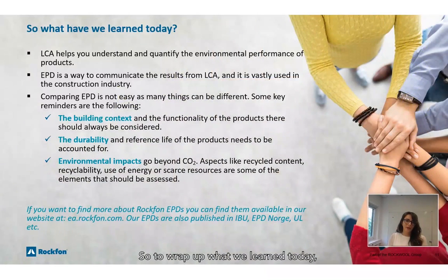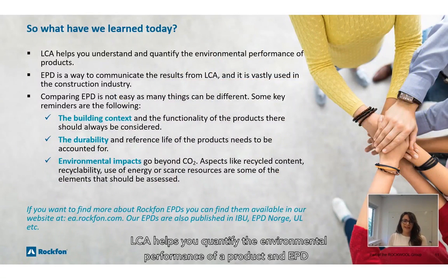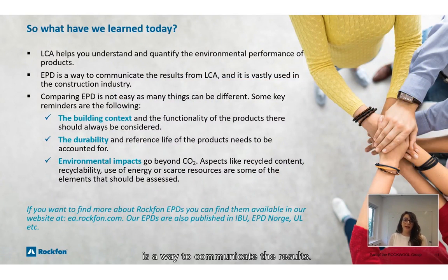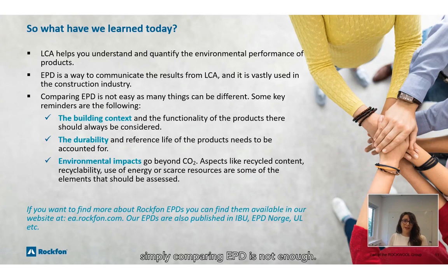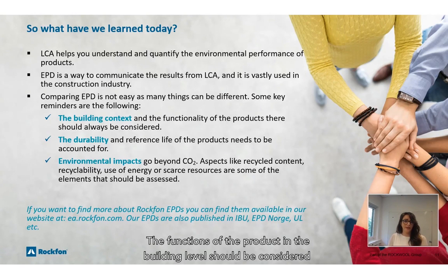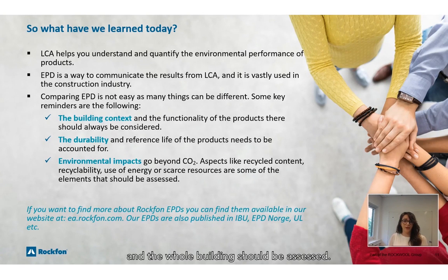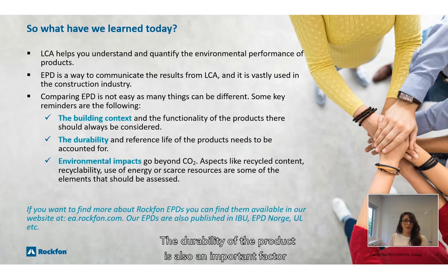So to wrap up what we learned today, LCA helps you quantify the environmental performance of products, and EPD is a way to communicate the results. In order to take decisions on which product to select for your project, simply comparing EPDs is not enough. The functions of the product in the building level should be considered, and the whole building should be assessed. The durability of the products is also an important factor.